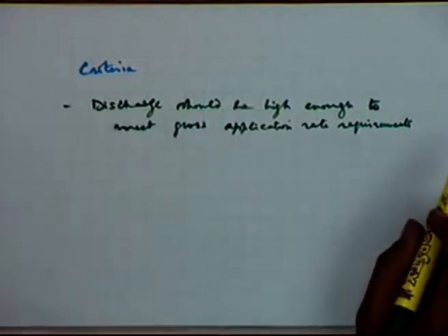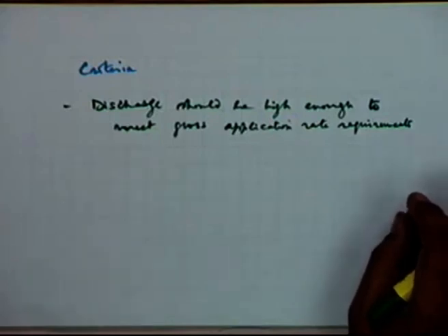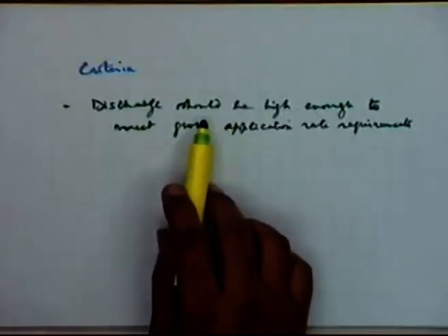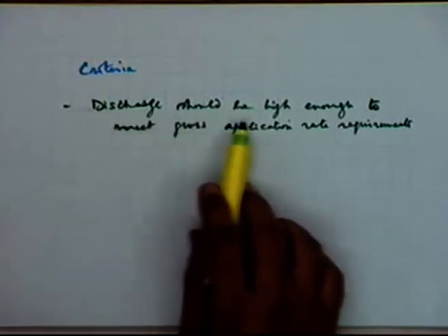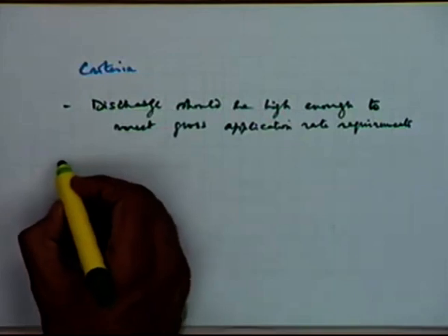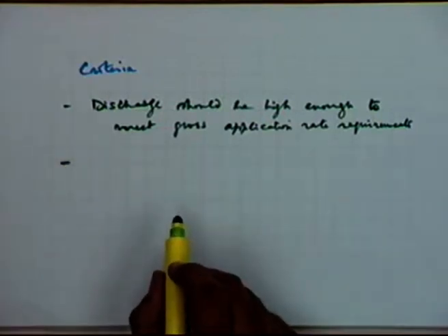Now you know what the gross application rates are. We have even looked at a table which we had formulated where we had given the gross application rates, which are desirable rates under the specific conditions. So you should intend to choose those nozzle sizes which have discharges high enough to satisfy the criteria of the gross application rate.